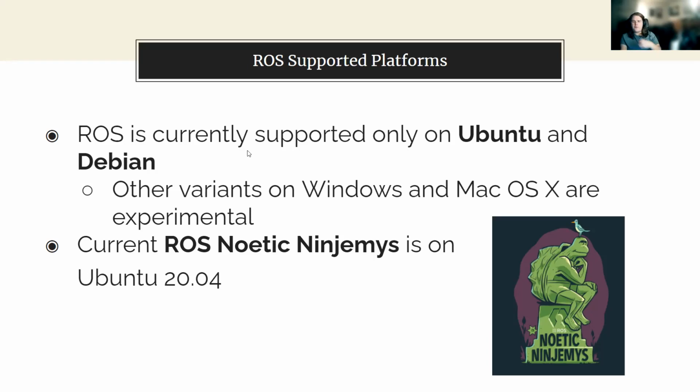There's also ROS 2, which is incorporating a lot of the changes that have come out of ROS in the past, I don't know how many, 14 years since it came out. But again, both are going to be supported right now, and ROS 2 is not as well documented. So if you're trying to learn this stuff and you're at a research perspective or just a student, I would stick with ROS 1 for now, right? They have plans to support both at once, and it seems like ROS 2 is still in active development. So stick with ROS 1 is my suggestion for now.